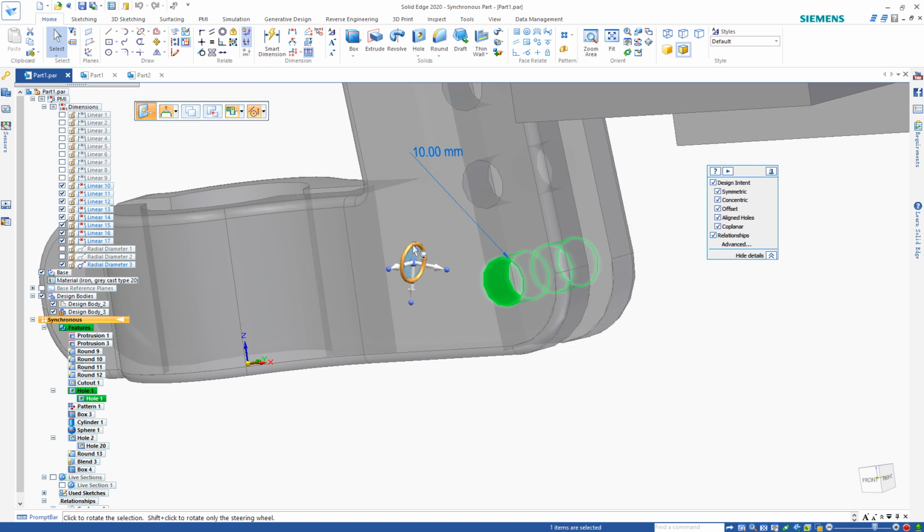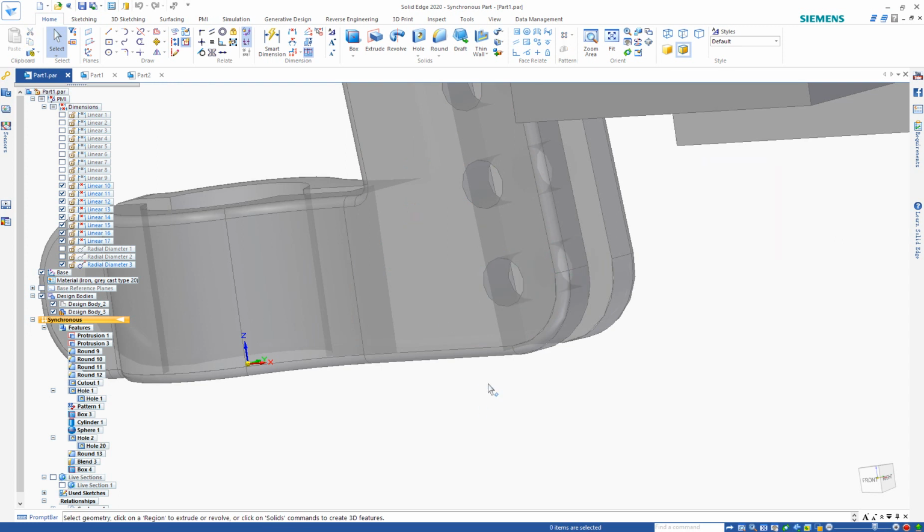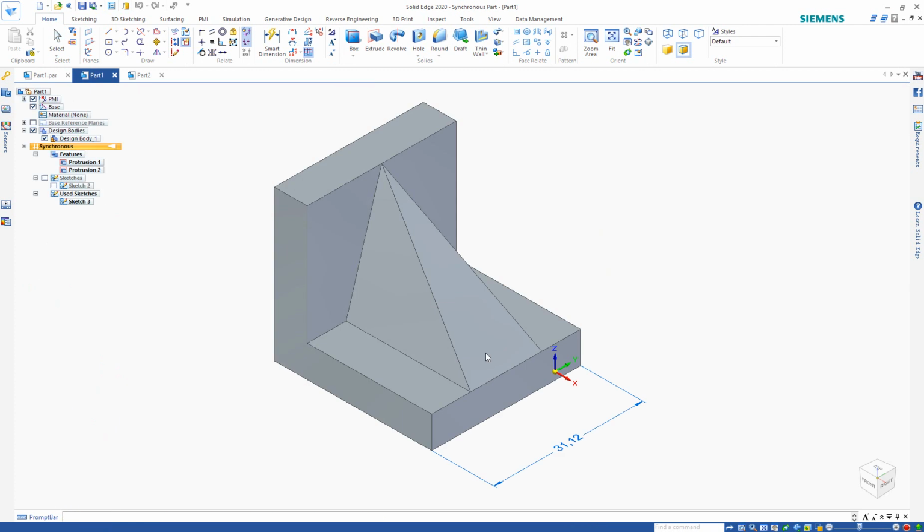Then this wheel that's used to turn has a wheel plane. If you hold Shift, then click on the plane, it will actually flip the plane. So it means you actually have all 6 degrees of freedom to do both 3-axle rotation and 3-axle movement. So this is the way you turn the wheel and flip it. All right, let's see 2 examples of how this wheel can help us.